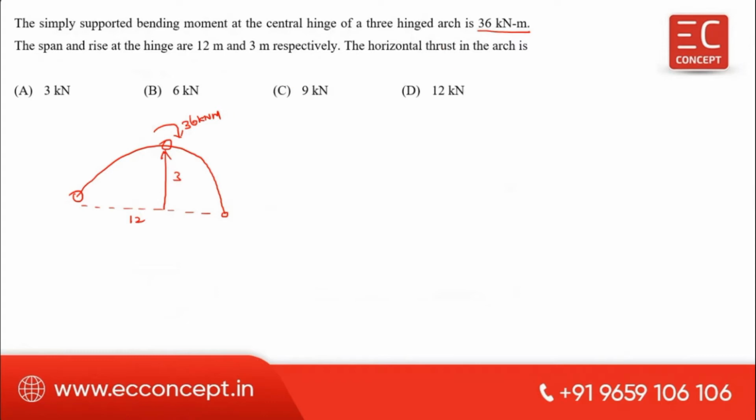So actually, this question is not fair. This question is not correct. The question is wrong. The reason is, this is the hinged end. The hinged end will not take care of any moment. That is a basic concept of hinge. What is the basic concept of hinge? Hinge only transfers the shear force or the kind of forces. But the hinged end will not bear any bending moment.